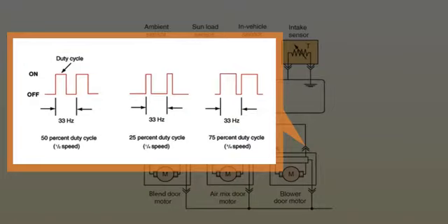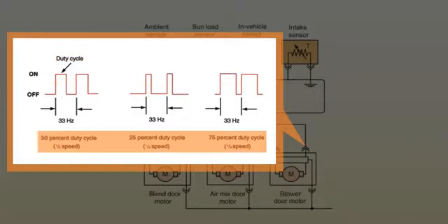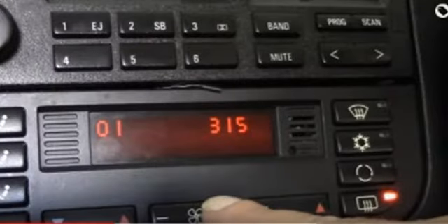The PWM signal that is sent to the blower is based on the on and off, duty cycle, and time during one cycle. Changing the ratio of the on-off time will adjust the speed of the blower. In the pulse width modulation circuit, the speed of the blower can be adjusted to any speed between the capabilities of the motor from the highest speed to the lowest speed. Diagnosing a PWM circuit can be done one of two ways.